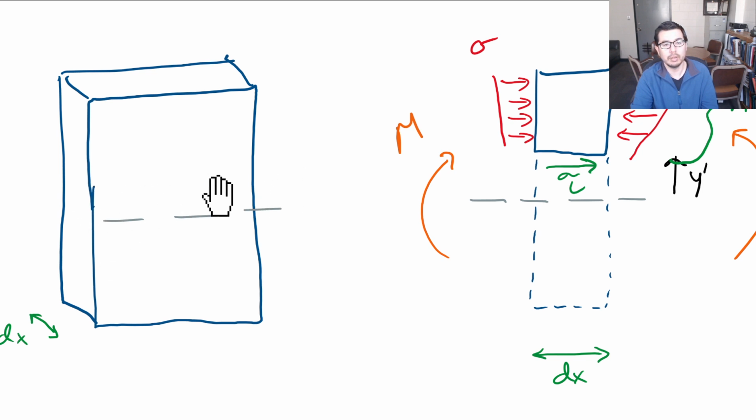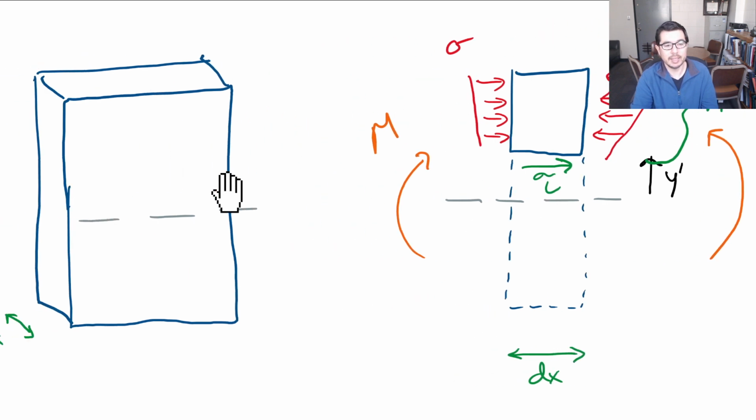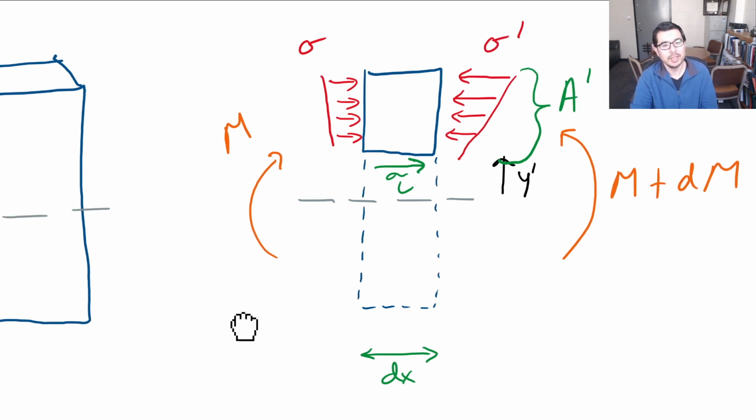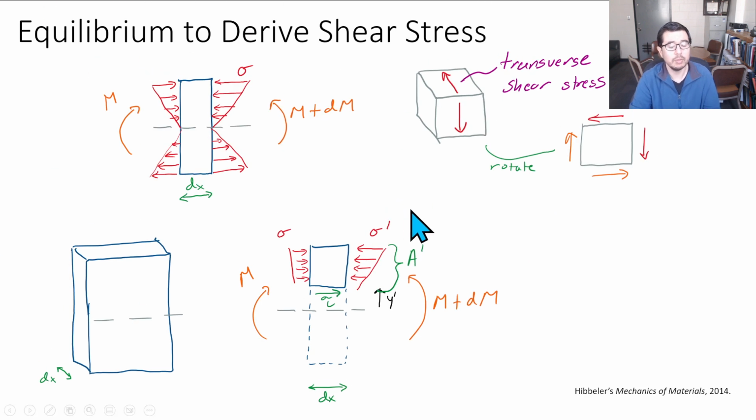We typically call that a B. So you would have something like a B or a T. In transverse shear stress we actually often use T. But that tau times that width times dx is going to be a force that can act against this sigma prime, acting over the width into this system and this height of this selected element, or the selected portion, better said, of the beam.